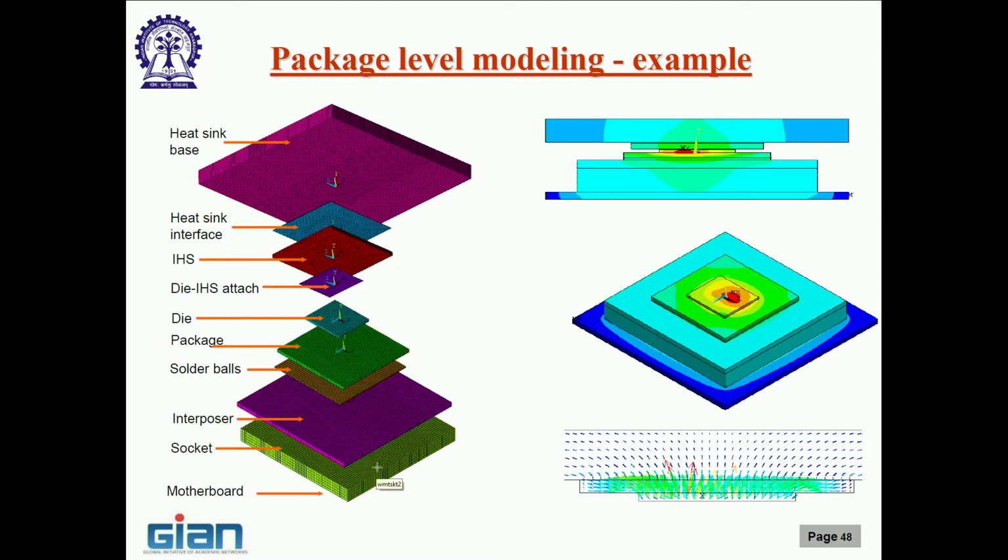So now the analysis is completely conduction based. Okay. 2D conduction, for all this spreading, it will capture, no problem. And this is an example of a temperature contour from the side view. As you can see, the silicon is the hottest, and then as you move up and down, the temperatures go down. You also see this non-uniform temperature distribution because of spreading, right.